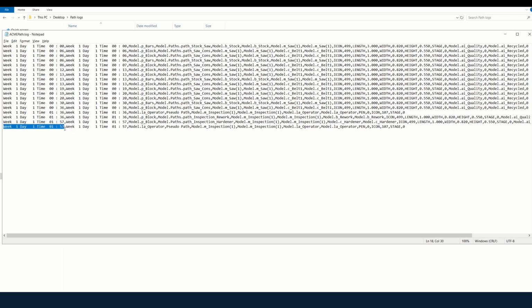Witness will generate a CSV file capturing row by row the journeys, entry time, exit time, the name of the part or labour, the type of path, the journey source, the path source, the path destination, the journey destination, followed by a list of attributes of the part or labour. Attribute filters can also be applied as shown for the vehicle journey logging.